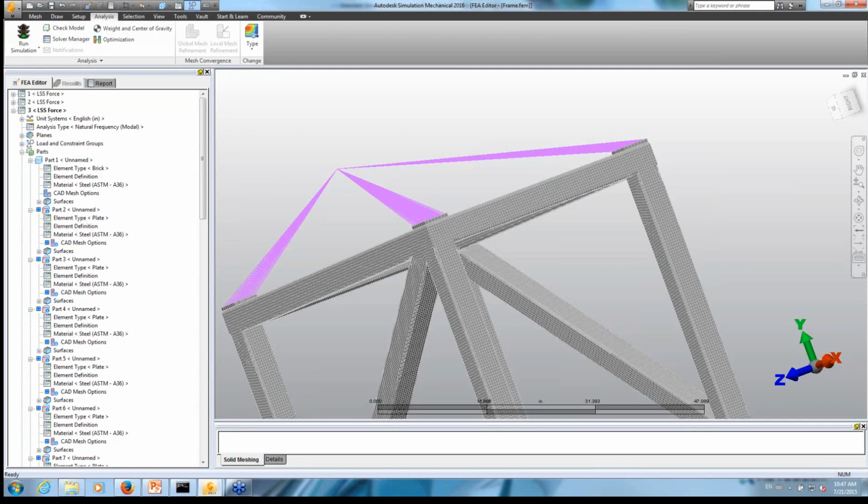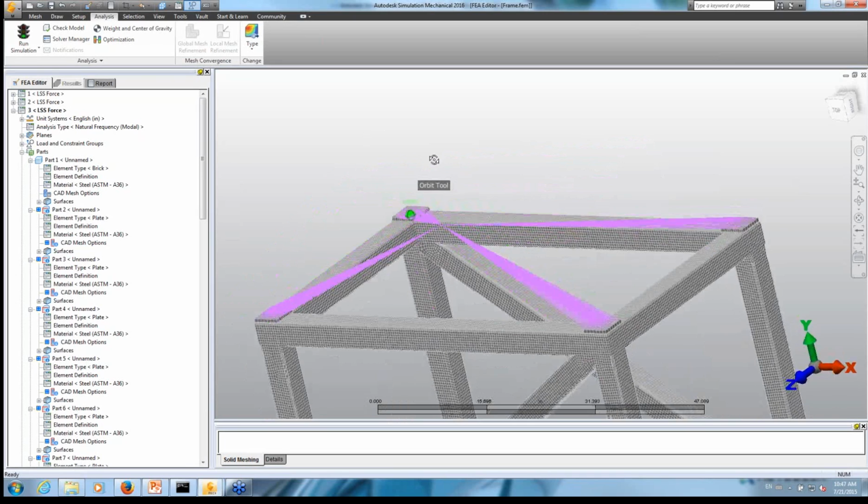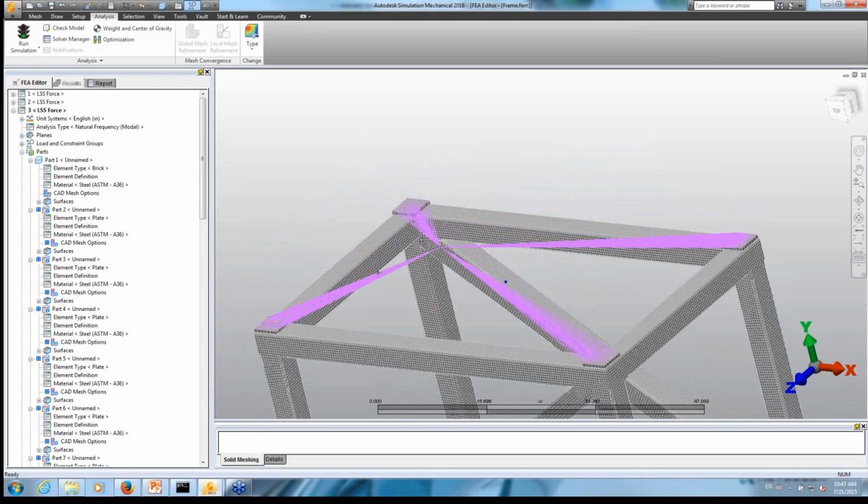That's right. You kind of had to know what you were doing. Yeah, but this latest version here doesn't actually allow you to define a force on the model. So just to see what the natural frequencies are, and by the way, those rigid elements will have an effect on the natural frequency of the model, in case you are wondering. They will stiffen it because they are connecting those 4 pads rigidly, which is probably not much of a deviation from real life. If you have a motor assembly sitting on those pads, that's going to be pretty stiff as well.